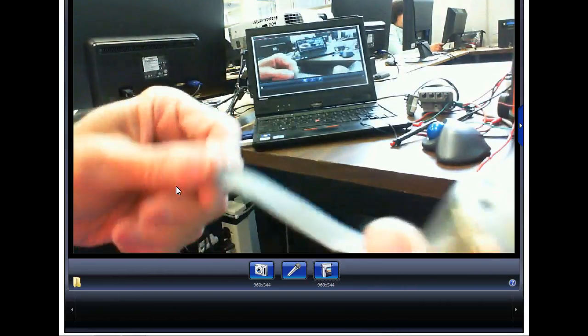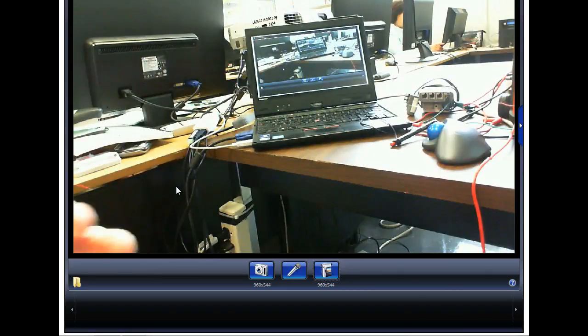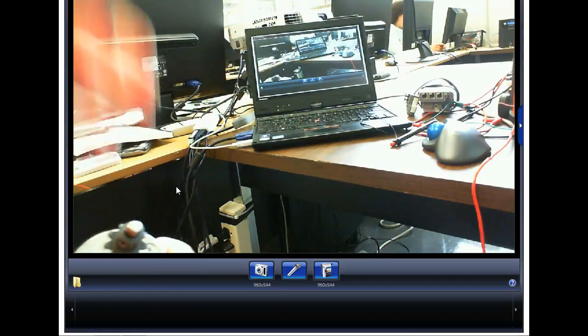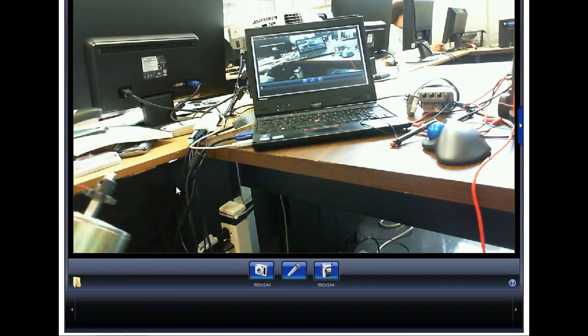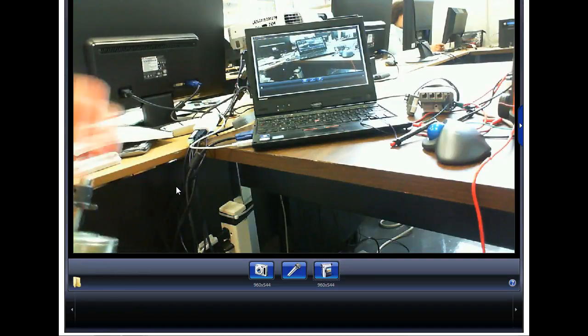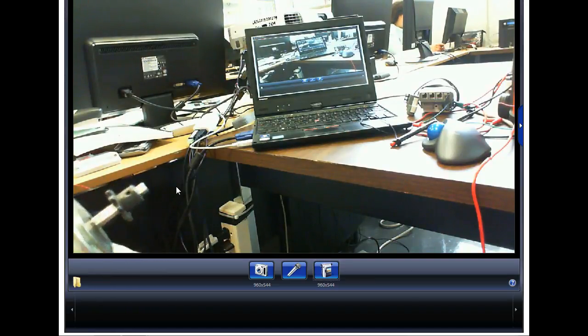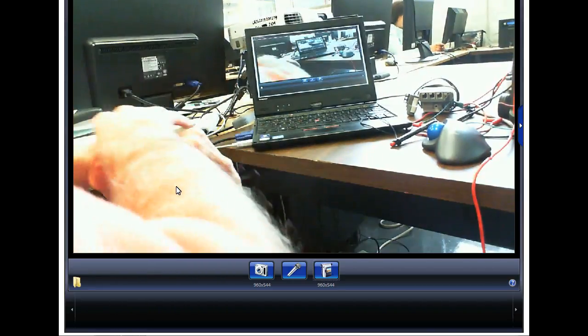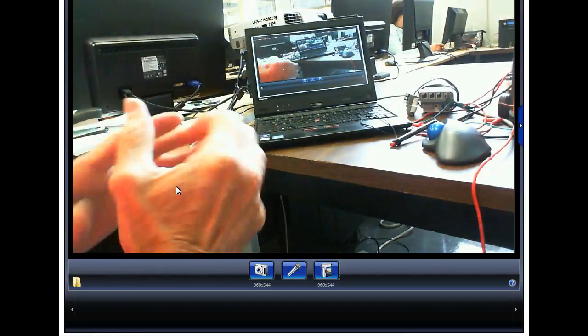This robot had some limit switches on it, so the encoders were not backed up. So what we did is we jogged the robot until it hit those limit switches, and then that was the origin of the robot. We can't really do that on these robots, so what they do is they put scribe marks on the robot, or they put indicators on the robot where we can set the origin. So yeah, that robot's no longer around, but it was a chain drive, so it actually changed between the servo motors and the